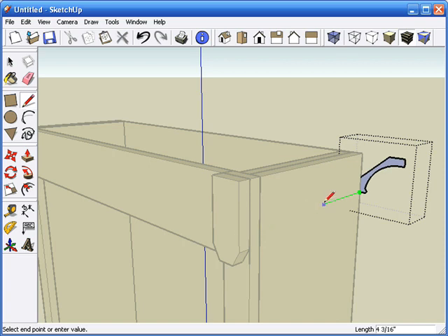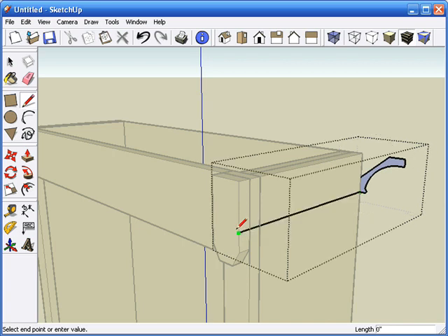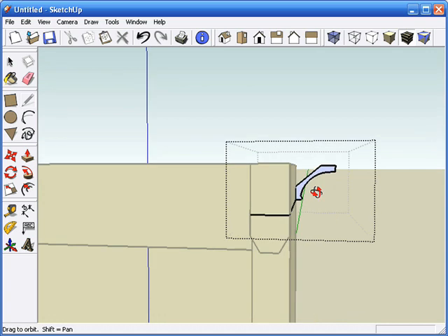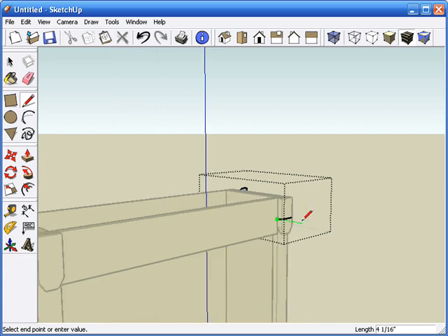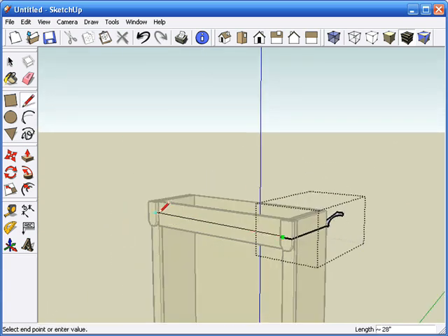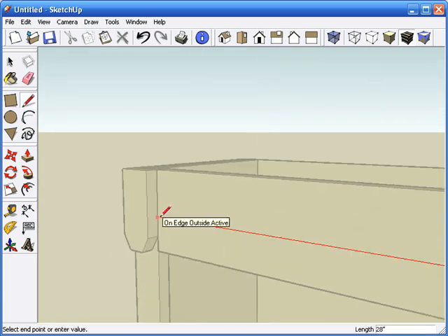You notice that that pencil line turned green. That means that it's square to the bookcase. It's level. It's on the right axis. I click there once. I come across and it turns red because I'm following the red axis, till I get to the other corner. Now I'm going to rotate the drawing around. It'll go green again. And stay with those axis lines. If you don't, you're going to get off axis and everything will be all messed up.